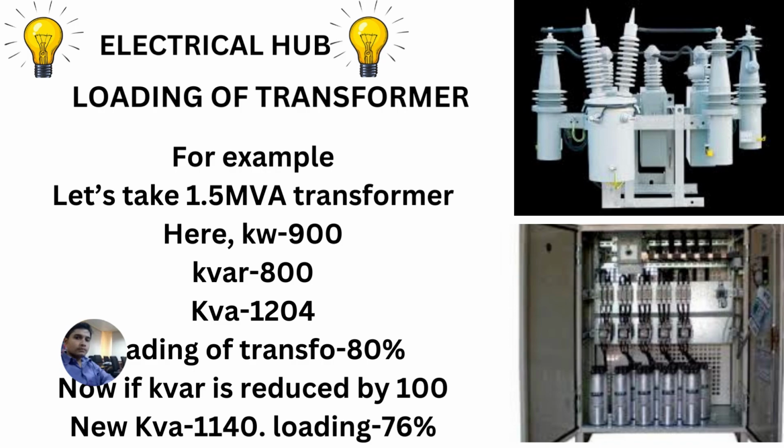Now, if we buy a capacitor bank of 100 kVAR, the new kVAR will be 700. Accordingly, the new kVA will be 1130. So, the loading of the transformer will get reduced to 76%. This is just for an example.